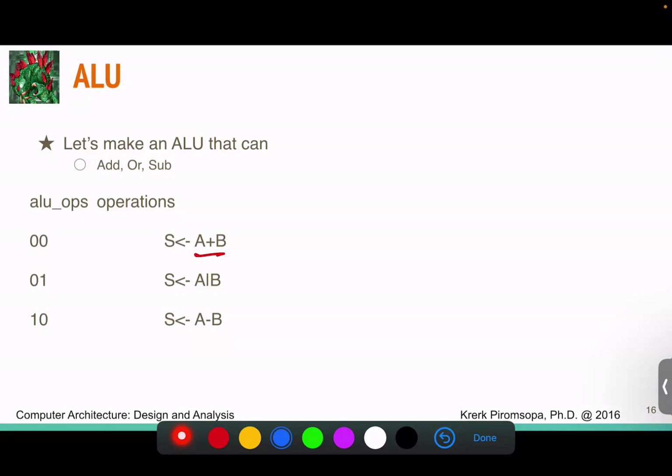Okay, it's like this. Again, this is a simplified version. We got full adders. What is a full adder? A full adder has two inputs A and B and a carry in, C in, and you get the result and carry out, like this. This is for one bit.